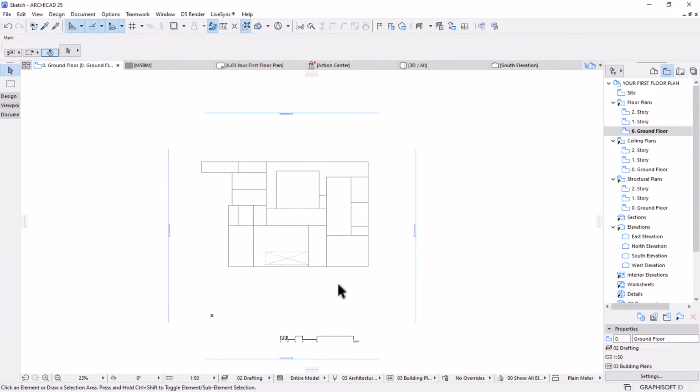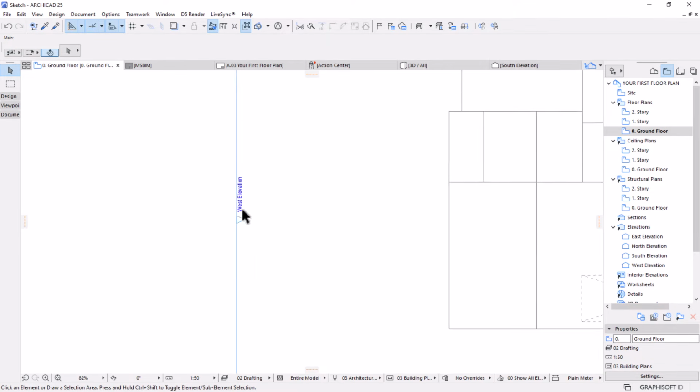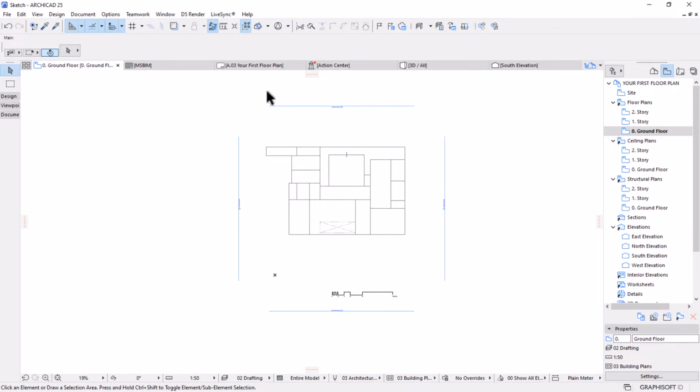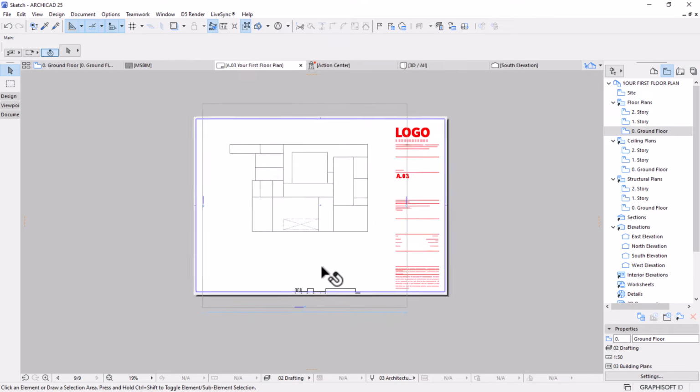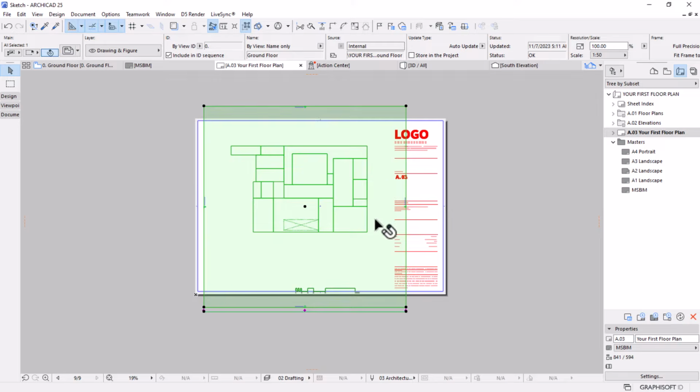All right, now we see our view has started to reduce the size of our elevation markers. If you go back here, you'll see our drawing has become big. So what I need to do is select the drawing, and then trim off the unwanted stuff. I'll click on this line or edge. Then we have a pop-out palette that gives you the tools for the specific situation. In this case, we want to stretch this to here, so I would go for offset the edge.